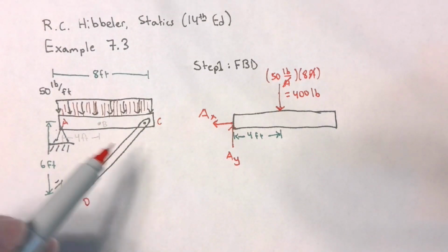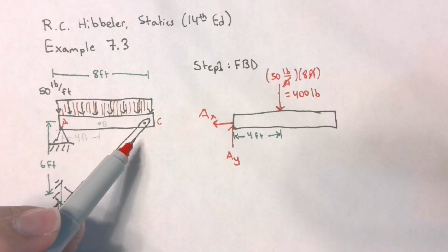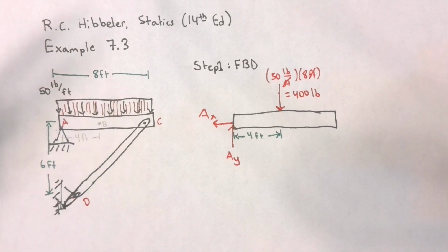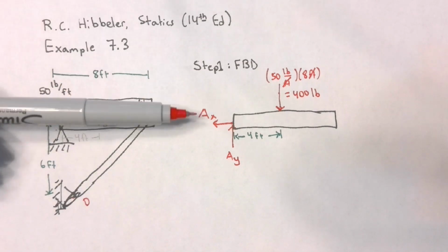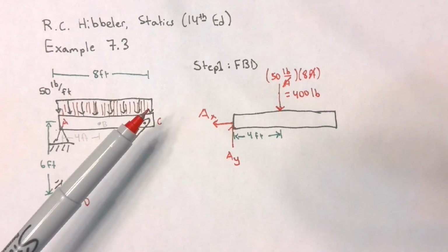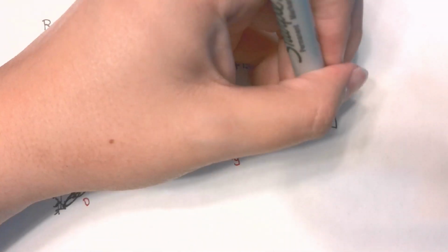A bar is not like a cable, right? A bar is a rigid body, which means that it can act in tension or compression. Just by looking at this system, you can see that we are applying a force that's making this rotate, and if this system is stable, this bar has to be pushing back. So the bar has to be acting in compression. That means that my force will be like this.